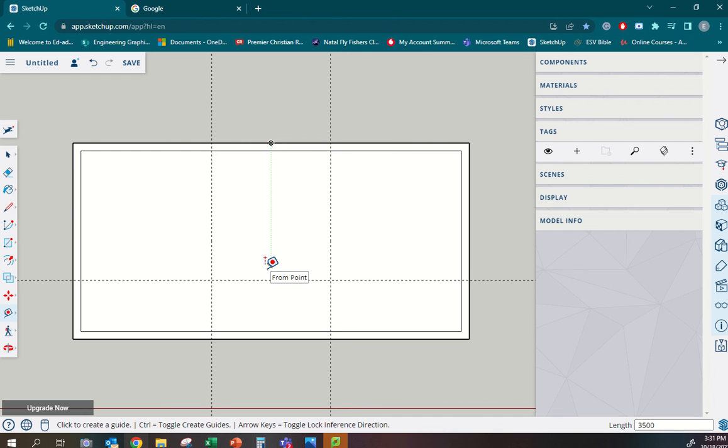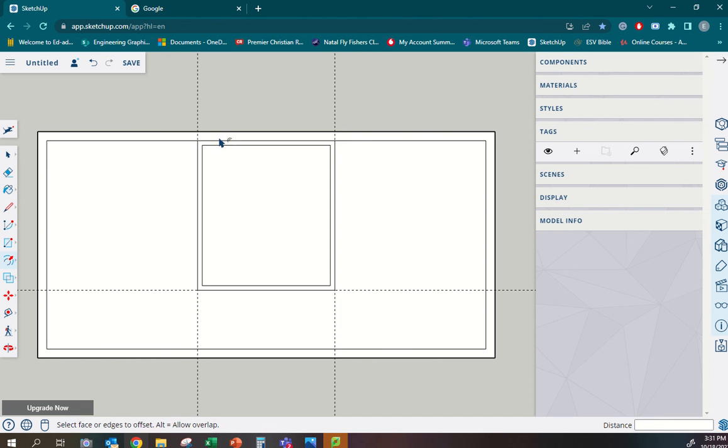So we have not quite a square, but we've got a nice rectangle, a nice space for a bathroom. Okay. And what I'm going to do now is click on my draw command, and draw out the walls along my guides. Right. Then again, offset command, click in that space, and I'm going to bring it in. Now I'm going to go 100 because it's an internal wall. So the wall is going to be 100 millimeters in width.